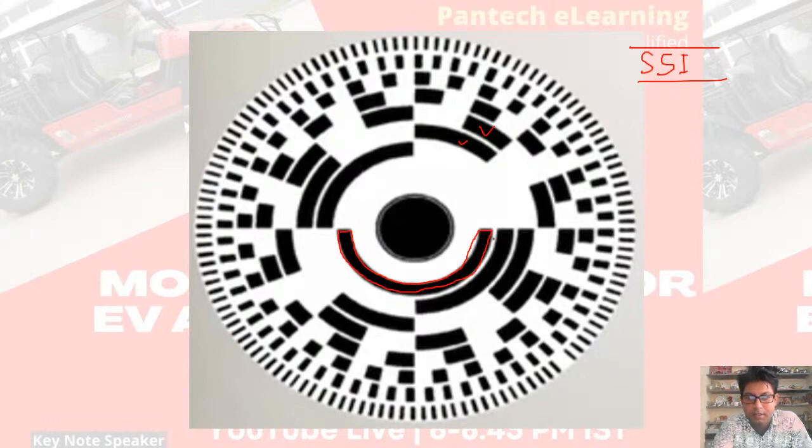Okay, so now you see, in the front side of the encoder, in the middle of each track, suppose I am putting some LED, and on the other side I am putting one photo detector. It is properly focused. That LED will be perfectly focused to the photo detector. Now what will happen if that disc is rotating?